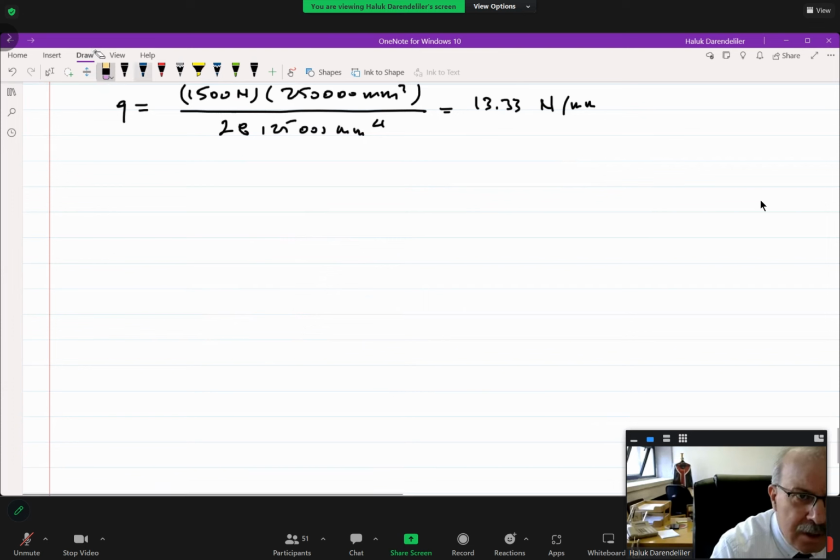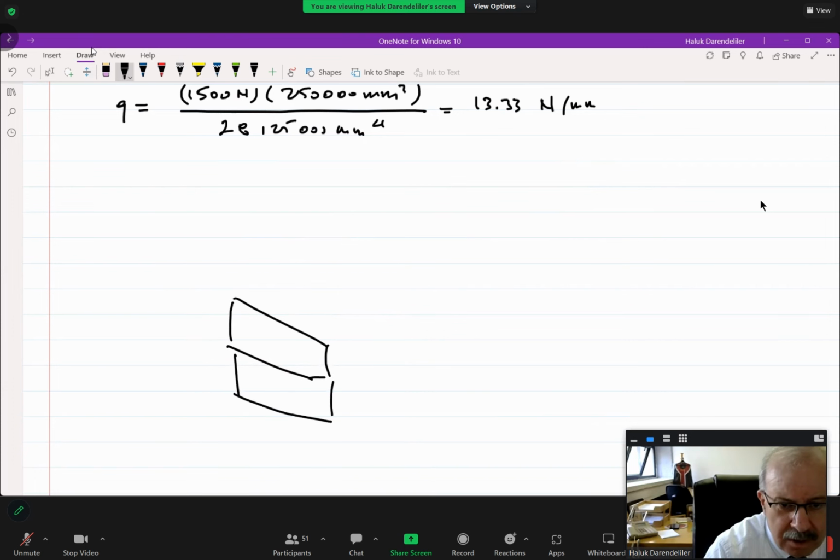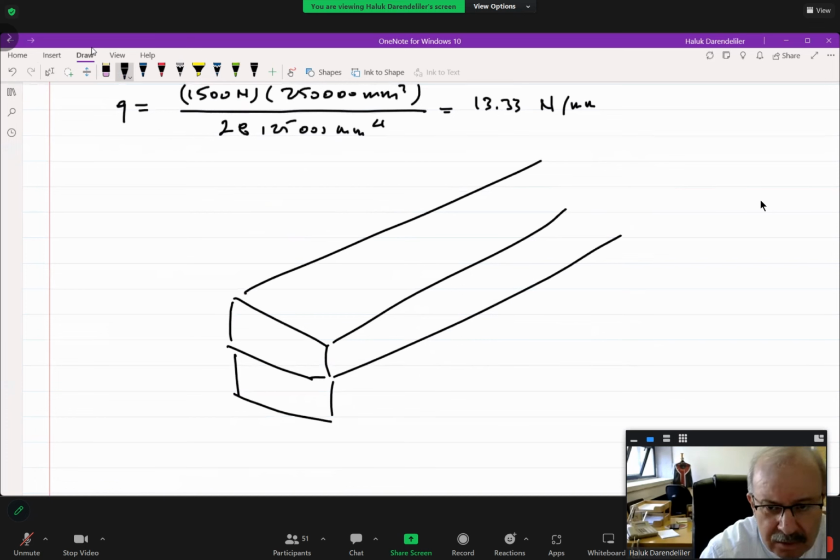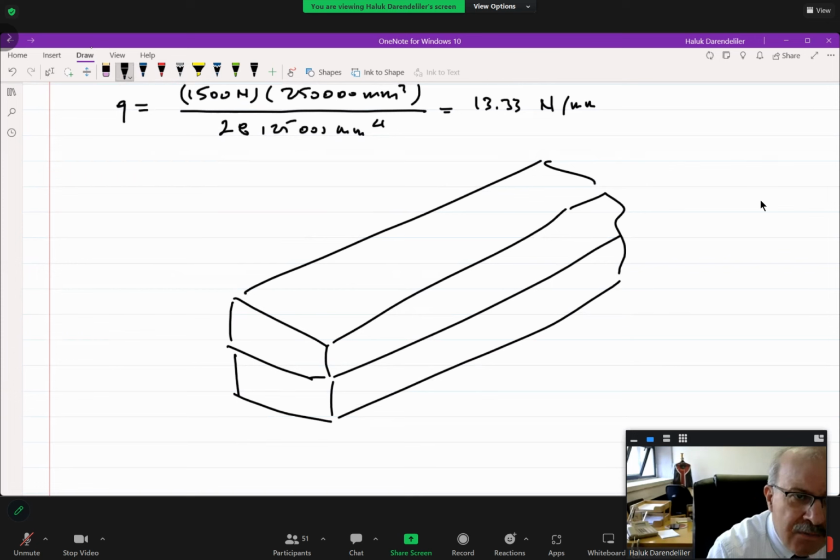Look. We have middle board here and lower board here, and they are going like that. Okay. Forget about their length. Say that they are infinite for our case. Now, we have nails. One nail, two nails. They are going like that. And I have shear flow on this board like that. Okay. On the whole surface. I can think that these two nails, for example, can carry the shear force which is defined on this area.